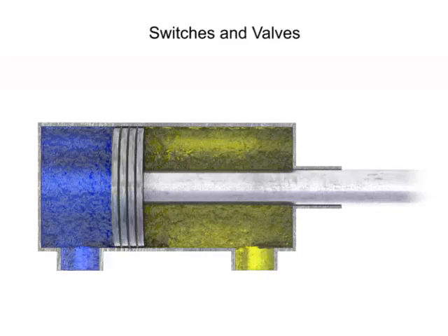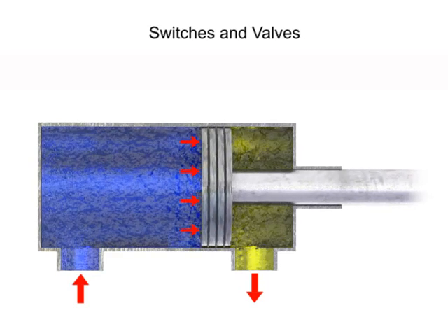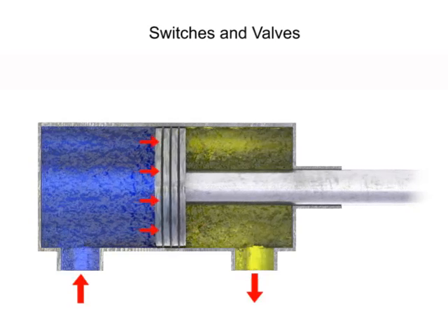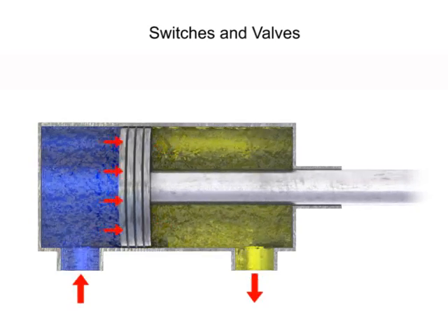The direction in which a cylinder piston will move or a fluid motor will rotate can be controlled by the direction of flow into the device. A cylinder is said to reciprocate if its piston travels back and forth, being reversed automatically at each end of its stroke without human operator attention.